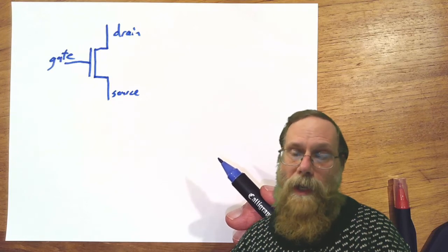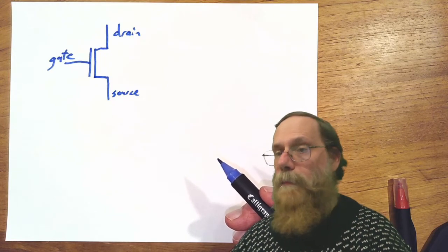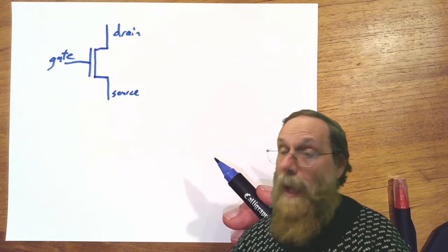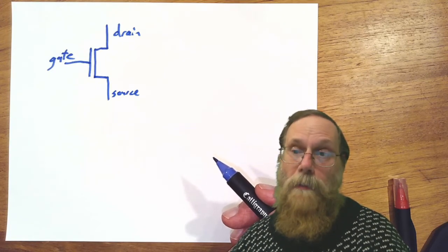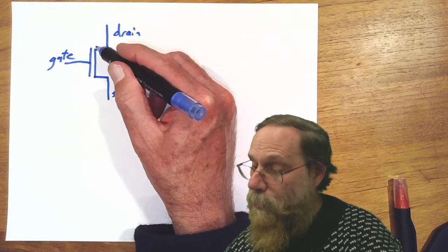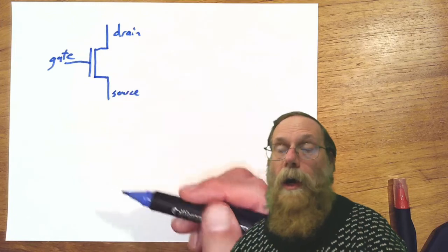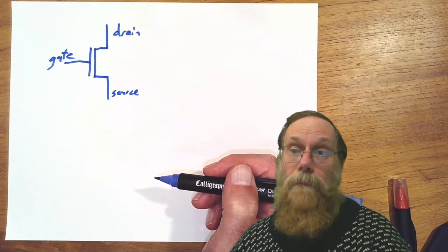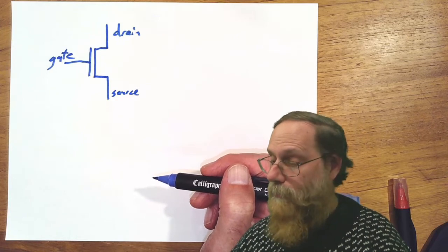All right, there are several different types of field effect transistors. We'll deal in this class with the junction field effect transistor, which we saw briefly for the microphone, and with two types of MOSFETs, N-channel and P-channel, which has to do with what sort of charge carriers are in this semiconductor region, the channel, that conducts between the drain and the source.